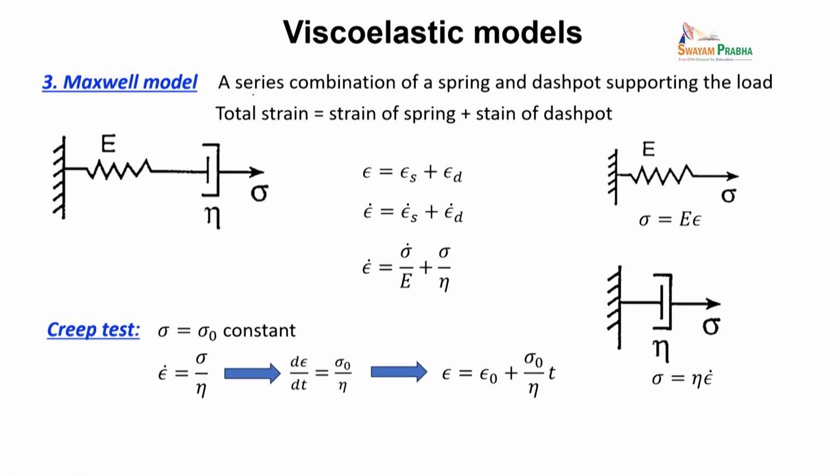It has a viscous effect, it also has an elastic effect. So you can think the model for polymer should be some combination of these two, so that it can have some elastic response as well as some viscous effects. That takes us to what's called the Maxwell model, very simple but very widely used to capture the viscoelastic behavior of plastics. In the Maxwell model, we have a serial combination of a spring to capture the elastic effect and then a dashpot that captures the viscous effect.